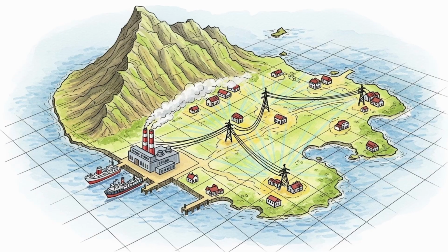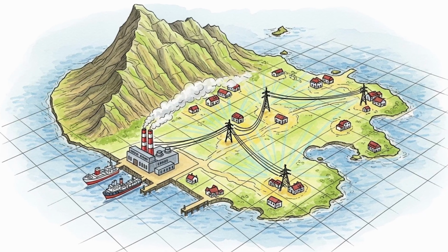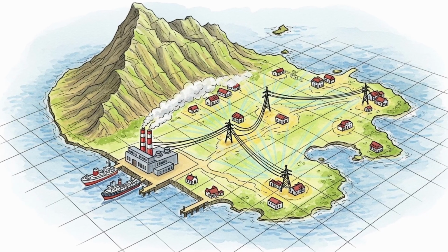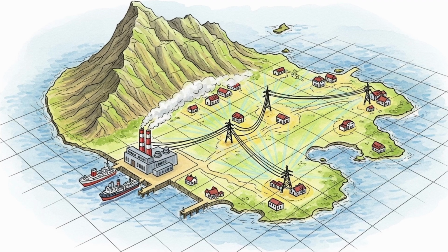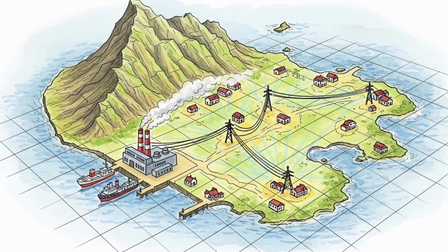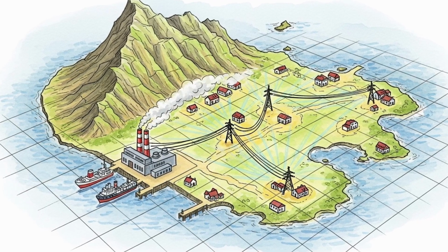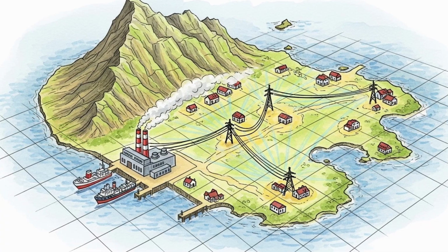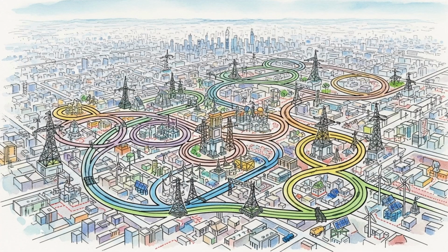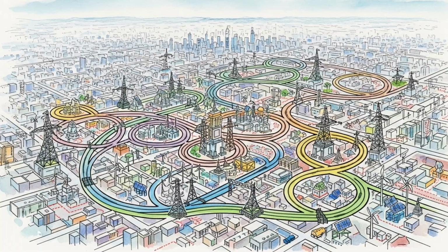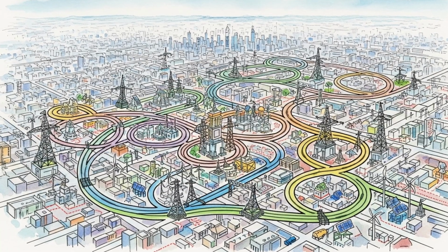Power systems see two kinds of stress. Solar arrays degrade slowly with radiation dose and suffer temporary power loss during high flux events. Cover glass and cell layout set the tolerance. Power conditioning units see more noise when charging and discharges occur.